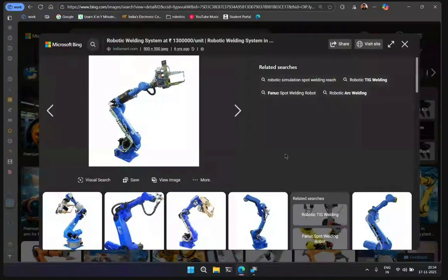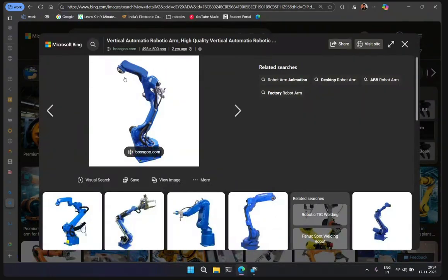What happens is if the robot is meant to carry 5 kg of weight, 5 kg is the maximum, but I put 6 kg. What will happen is the joint at which the end effector is attached, this end effector joint, will just break off.